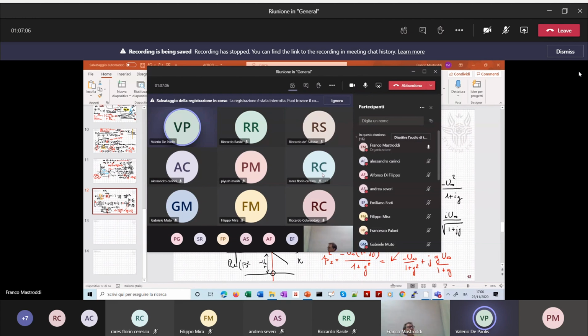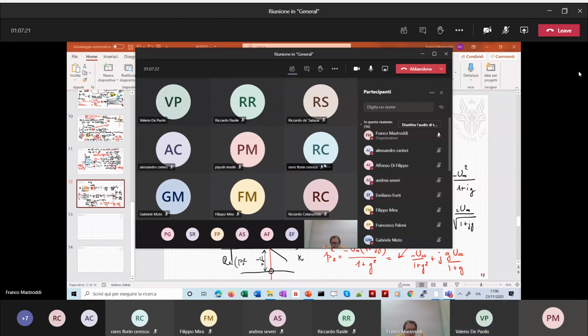No error, because you are working on the imaginary axis, and you are evaluating your aerodynamic matrices correctly on the imaginary axis, so there is no approximation. If you have converged to a value for your critical value, you are not doing any kind of approximation, because you are on the imaginary axis. You are not able to evaluate stable poles in any case, but only the margin condition.